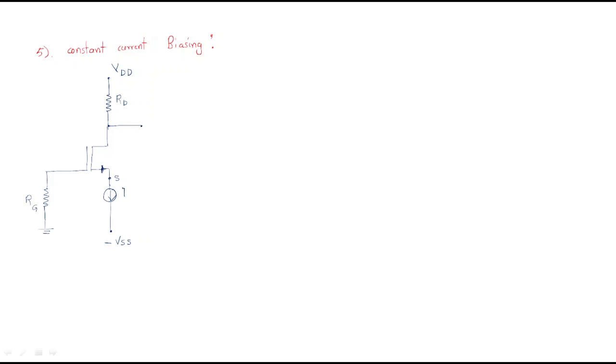Here, look at this. This is also the same symbol. Don't confuse it; sometimes it will be given like this, no problem. Remove the V0 and just look at VDD, which has resistance RD and we have the constant current. Whenever you put a constant current, then any variation in the circuit parameters causes no change in the output current. Output current should be fixed.